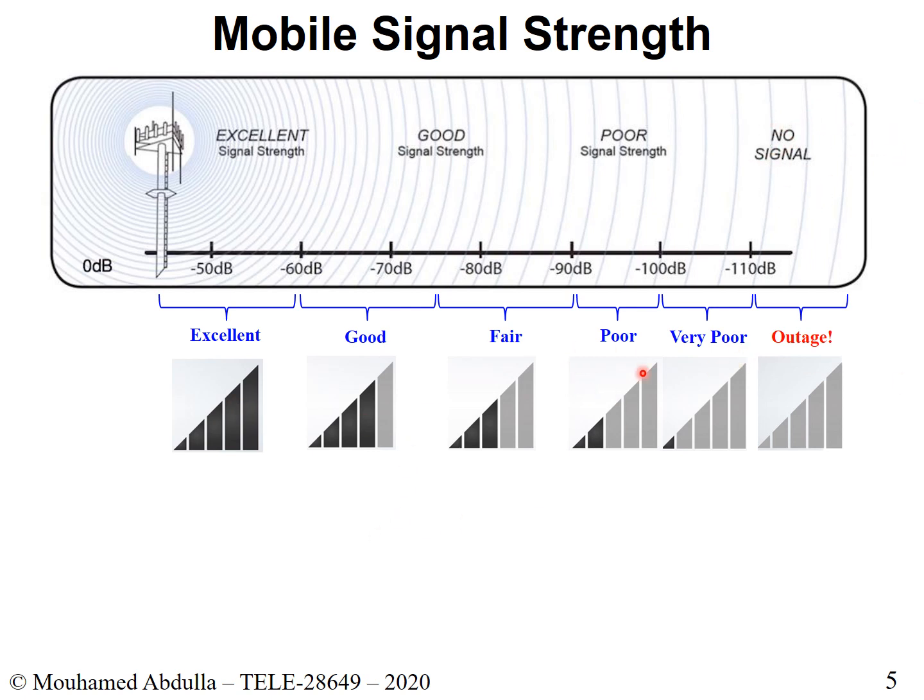Whereas here we see more descriptive, because with Samsung phones you generally see 5 bars. So that's just the way the different manufacturers design their device. So you shouldn't worry too much about it. But in general, this is kind of the description that we have in terms of power. So one thing to remember, as I said to you before, consider minus 110 dBm of receive power is basically the really absolute threshold after which your signal is completely in outage.